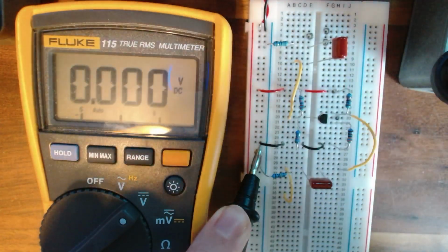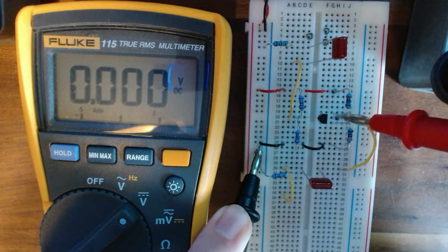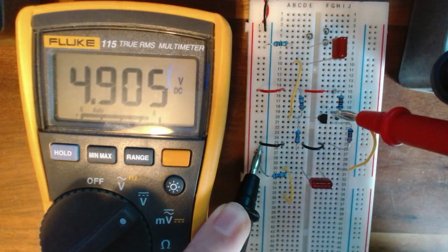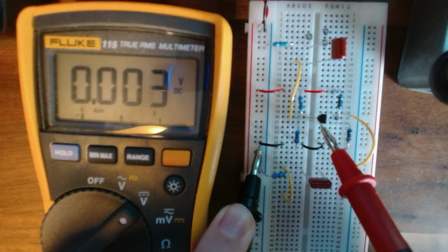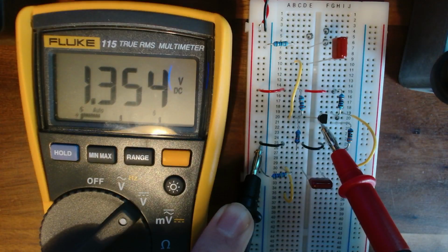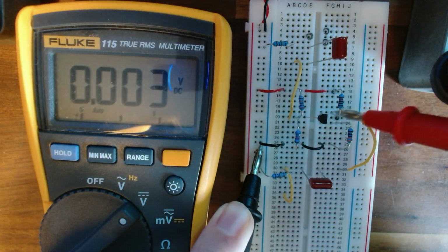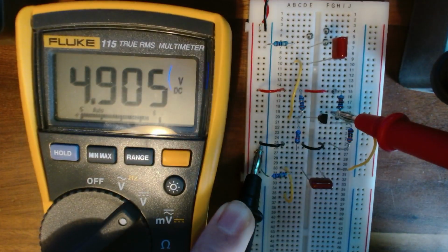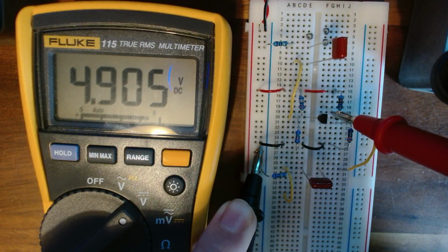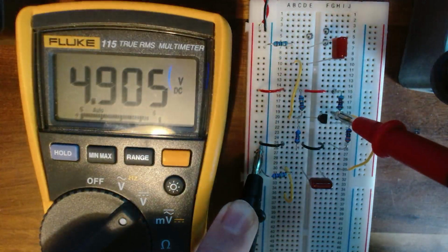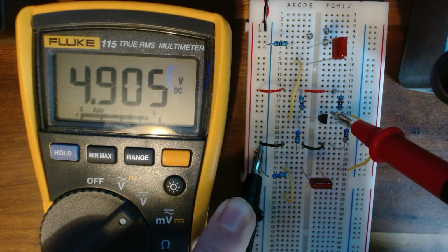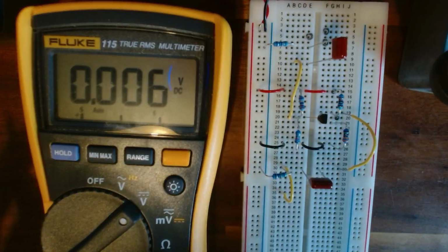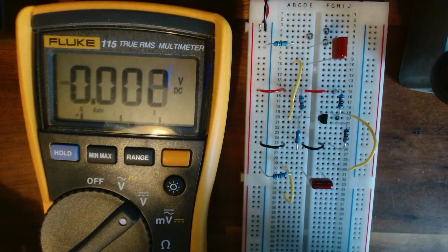And then we can double check our collector, and we should see about 4.5. We've got 4.9, but again, if we've got 1.3 here, that means that a little bit more water is flowing through, which means we'll get a little bit more voltage at the top. 0.4 volts is fine. We're not going to cause any damage to anything with that little bit of variation. In terms of real world spec, this circuit is behaving perfectly.